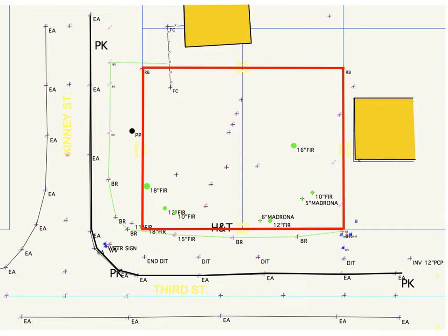The next thing is these are the two adjoining existing houses. They're mapped pretty closely so we can understand things like setbacks and shadows and views, etc. This was the line of the brush. The site was overgrown, and the brush didn't just stay on the property, it extended into the public right-of-way. So the surveyor mapped the edge of that brush line so we could understand it. And then an important thing was an incursion on the site. The neighbors had built a fence that went onto our property. So that was important to know.